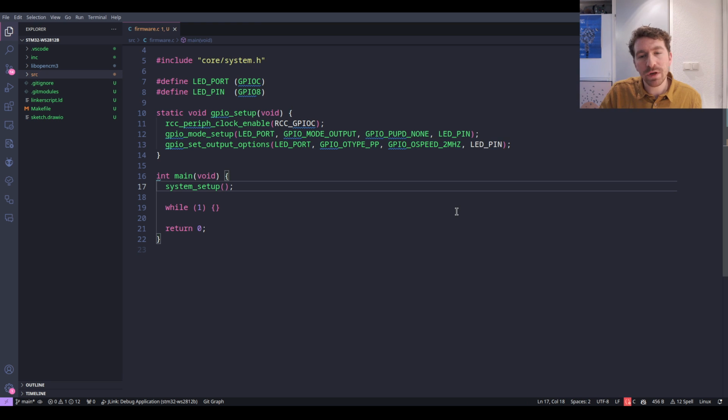Yeah, but basically what I want to make sure is that we're able to transition the signal at the right speed. If you don't transition fast enough, then your signal will come out distorted. Basically, you won't be able to make the right timings, and if you go too fast, well, you get really sharp edges, but you'll spit out electromagnetic radiation everywhere.